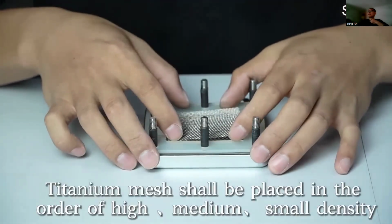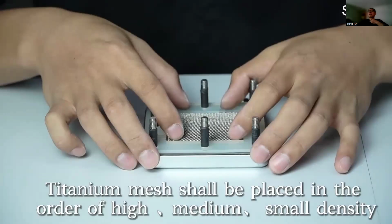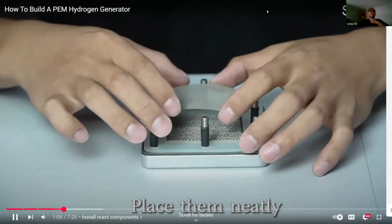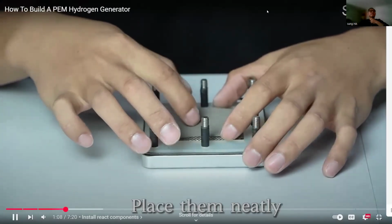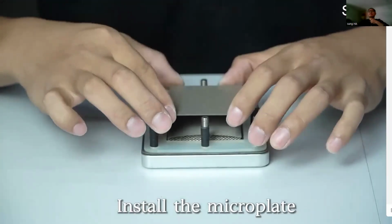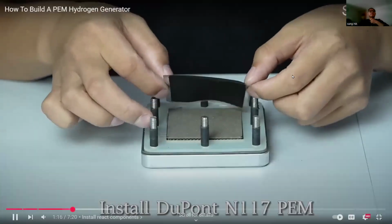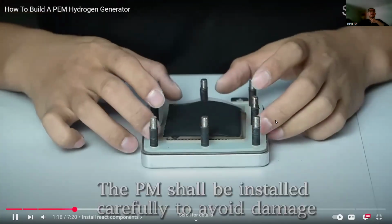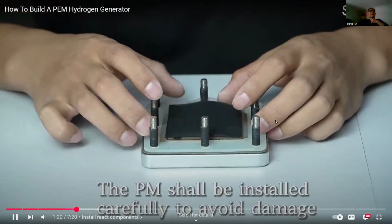Titanium mesh shall be placed in the order of high, medium, small density. Place them neatly. Install the microplate. Align the titanium mesh when placing. Install DuPont N117 PM. Okay, this is the PM. So through this PM, proton will travel. The PM shall be installed carefully to avoid damage.